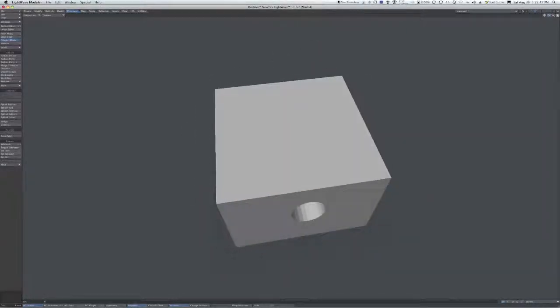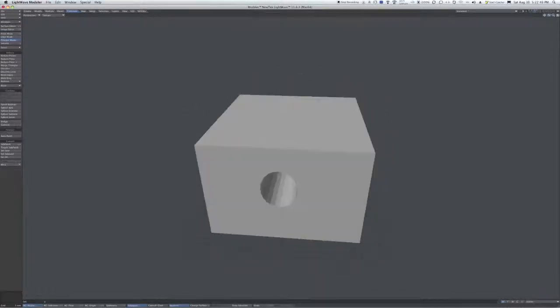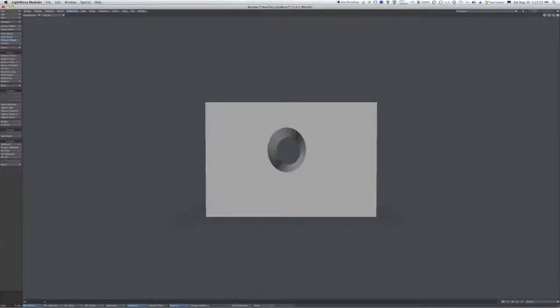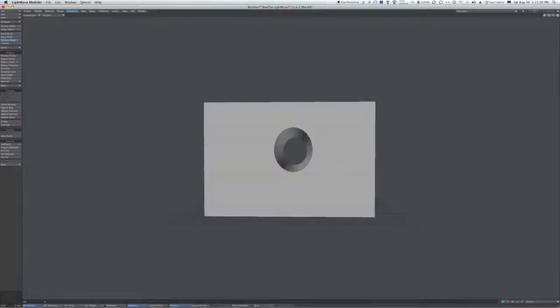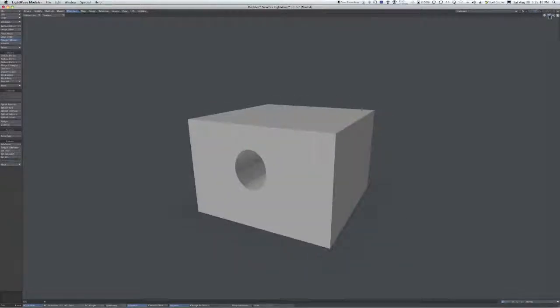And so 1 to 2 millimeters is a normal excess. Actually, it's more closer to 1 millimeter for the average hole, but it all depends on the size of the hole. Like a 1 millimeter hole will probably print solid. A 2 millimeter hole will print like a pinhole, but when you get up to like 3 and 4 millimeters, then they become a normal hole. So that's another item that you can look at.